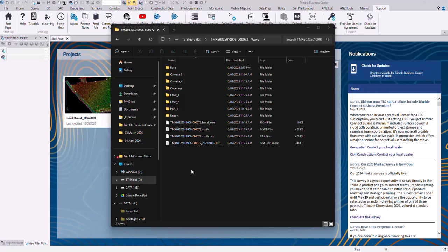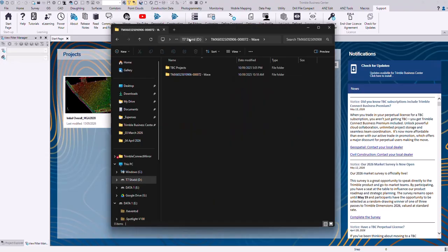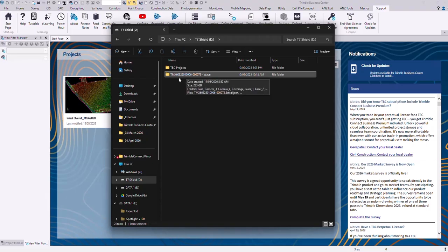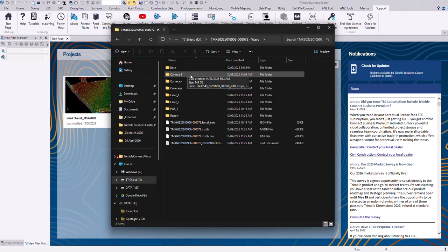Guys, just looking at the Trimble MX60 data workflow in this T7 Shield drive. I've got two folders, but we'll look at this file first here. This is the raw data file that we've dragged off the two 4 terabyte hard drives. It comes in two different drives, but you just collate them together into this one package.